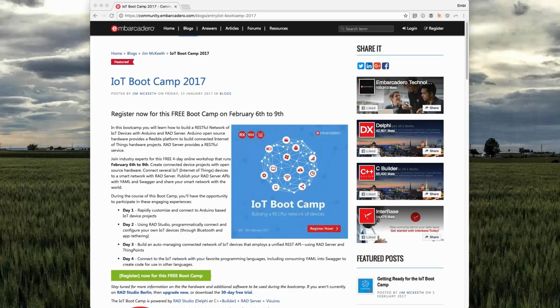The Nano's example and the Uno are among the most basic boards, so their memory is quite limited. We're talking about something like 2K of memory, right? So it is not that difficult to exceed this type of memory. On the other hand, if you have something like a Mega, you can almost pour anything you want into it. It usually is going to take it. Right? Okay. So it just depends how powerful the controller is. Okay, that was good to know.